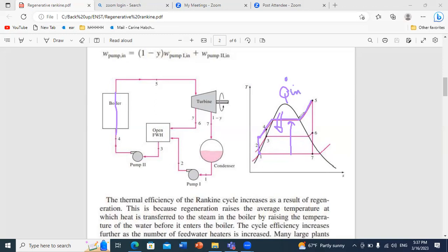and we keep heating. It's good to heat more. Why? To get rid of the disadvantage of having low quality at the exit of the turbine. Because by comparing with the conventional Carnot, if you leave at this stage, for example, or if you do more superheating, you can leave at the desired level, which is, let's say, 100% vapor, at the exit of the turbine.